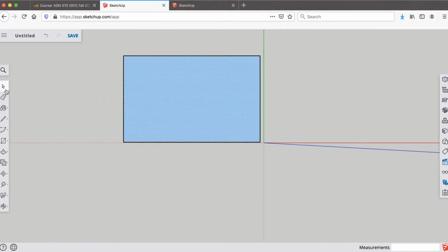Okay. So from here, I want to double check to make sure I entered everything in correctly, and I also want to double check that my units are reading correctly like they should be. You have this tool, it's a tape measure tool. It's going to measure. See, it says length 24, and that's just if you want to make a measurement but you don't want to leave a mark, right? 24, 15, that's correct. But if I want to be able to visually track this, what's great about this little tool right here, let me hover over, what does it say? Dimensions is what it's called.